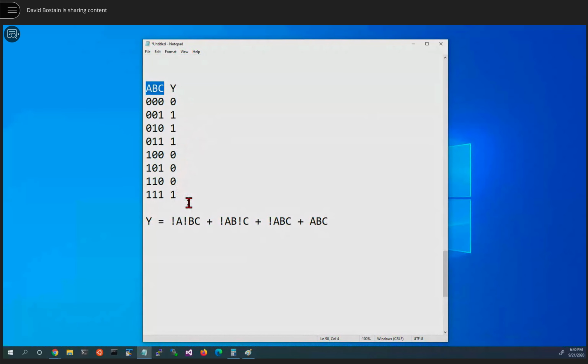And we call a particular function a gate. So for example, when I write down y is equal to AB, I'm going to later call that an AND gate. I write y is equal to A or B. I'm going to call that an OR gate. And you'll see why later, because they apply to components in electrical work that are called gates. Because they're basically gates of the logic. The logic input gets gated so that it either goes through or it doesn't based on the equation you've given it or the way the chip was built.